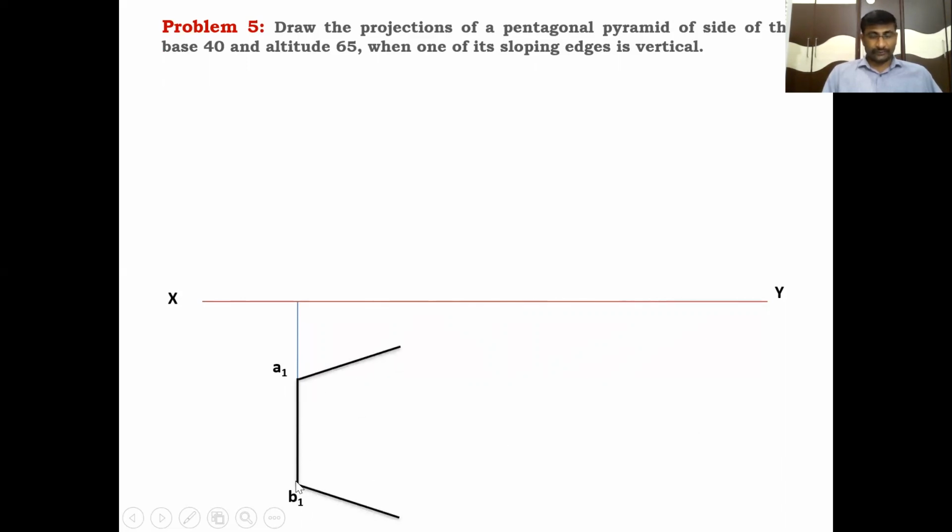Join 2 inclined lines. So draw 2 inclined lines, which make an angle of 108 degrees, because the angle between any 2 sides in the regular pentagon is 108 degrees. Like that, place the protractor at A1 and draw an inclined line which makes an angle of 108 with this initial A1 B1 line. And place the protractor at point B1, join an inclined line which makes an angle of 108 degrees with this A1 B1. Clear? Draw these 2 lines with 108 degrees.